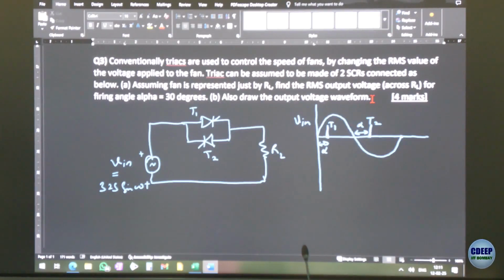One is that you can inject some resistance in series, which would create an IR drop and lead to a lesser voltage at the winding terminal, right? So you can put a series resistance which you can keep changing as you go from speed 1, 2, 3, 4, 5. The resistance can be slowly removed from the circuit. So at speed 5, you directly connect the input voltage to the fan. At speed 1, you have a large resistance in between.